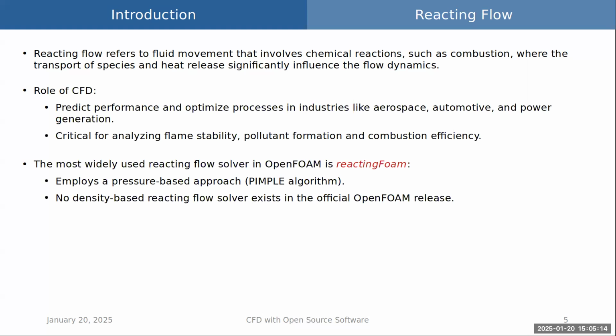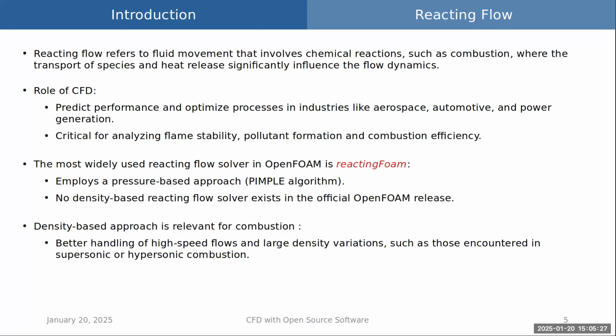In OpenFOAM, the most widely used reacting flow solver is reactingFoam, which employs a pressure-based PIMPLE algorithm. However, there is no density-based reacting flow solver currently available in the official OpenFOAM release. And a density-based approach can be relevant for combustion because it handles high-speed flow and large density variations better. It also captures acoustic wave dynamics, which are crucial for understanding the interaction between heat release and acoustic phenomena, which is especially relevant in systems with thermoacoustic instability. So this highlights the importance of developing a density-based solver for reacting flow.